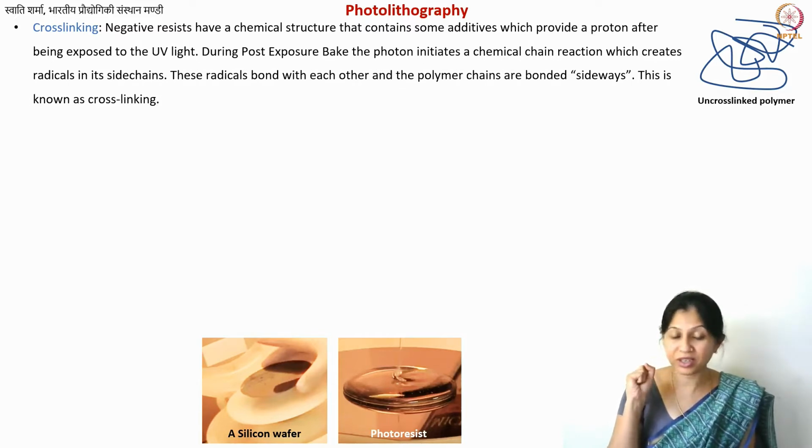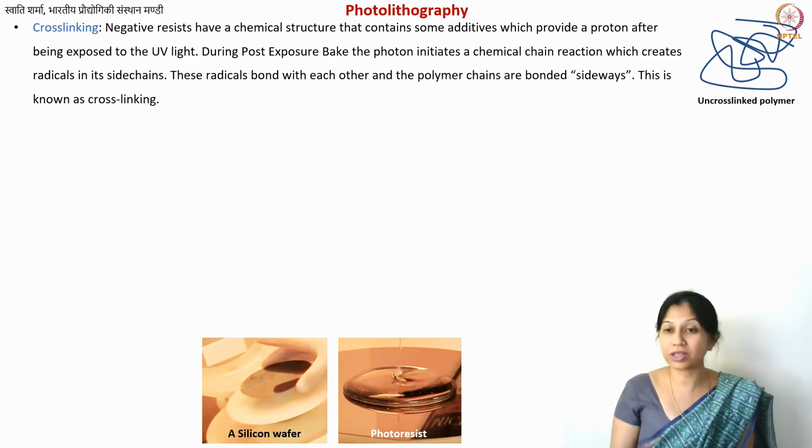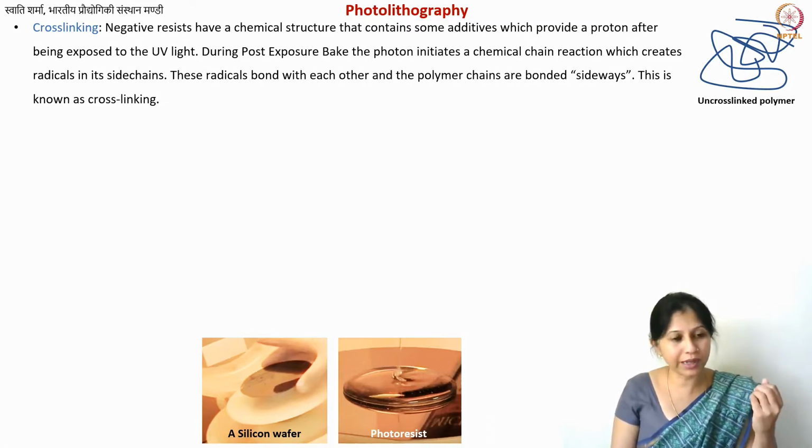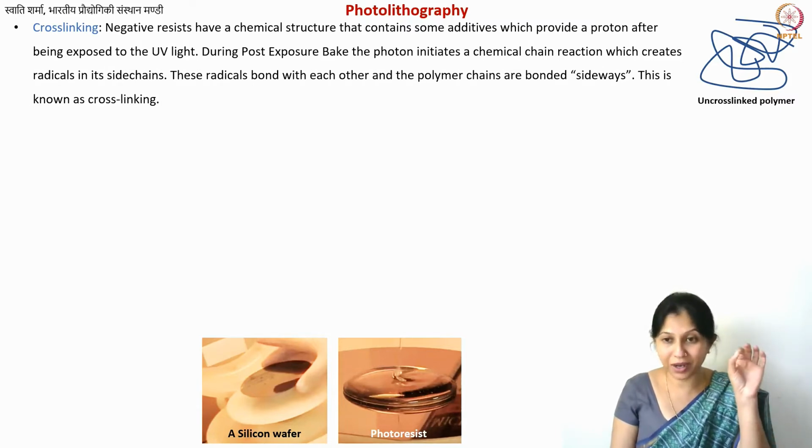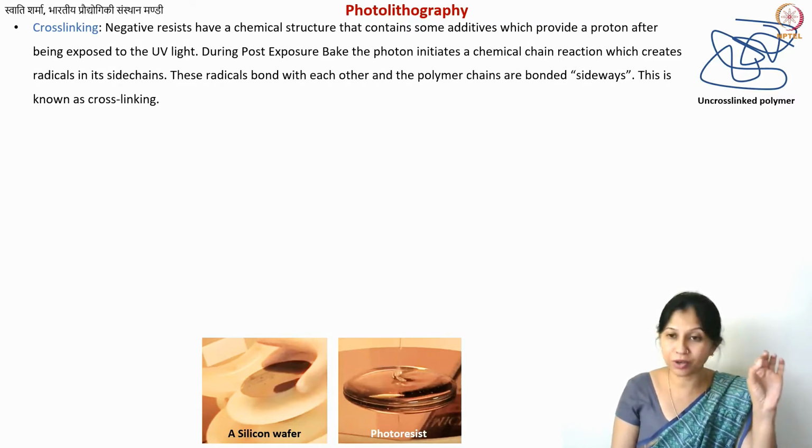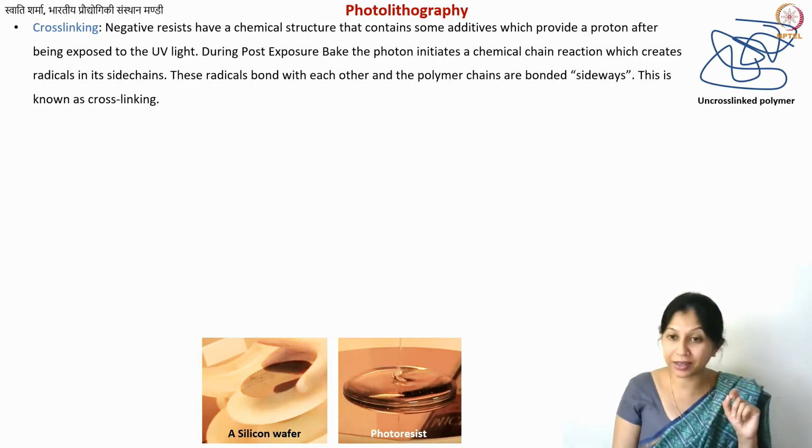Photoinitiators are materials which are very sensitive to the UV light, and that is number one. And number two, when they absorb light of a certain wavelength, they undergo a chemical reaction which releases, let's say, a proton. That proton will then hit your epoxy bond and open it. In that reaction, another proton is generated, and this is how the chain reaction continues.